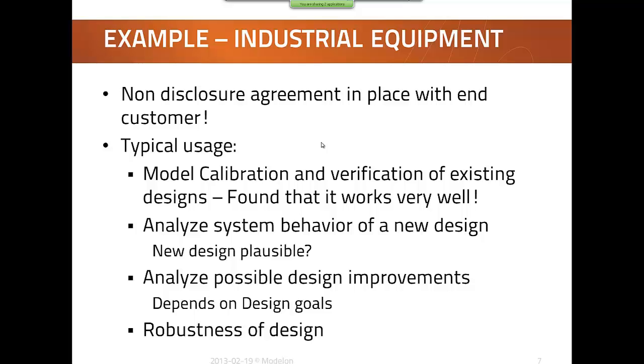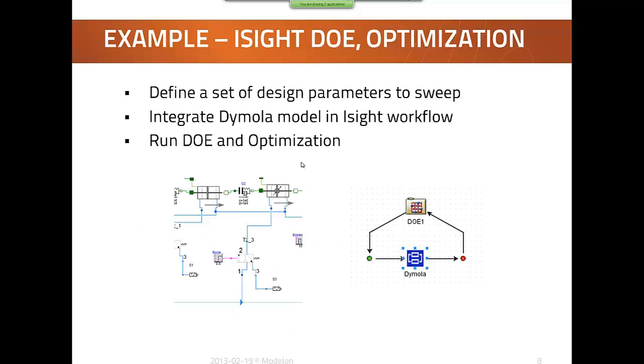They can take it even further than they would normally do to create completely new designs that they wouldn't think of before, to see if it's possible or plausible to do this kind of crazy designs. And they also analyze possible design improvements and robustness of their designs. And one thing that we did that I can mention here as well is we used Dymola and the Pneumatics library in conjunction with ISIGHT to do design of experiment, to do parameter sweeps and optimization. And this worked very well.